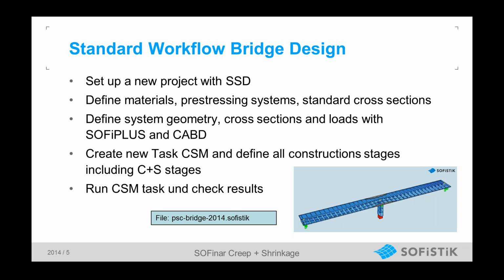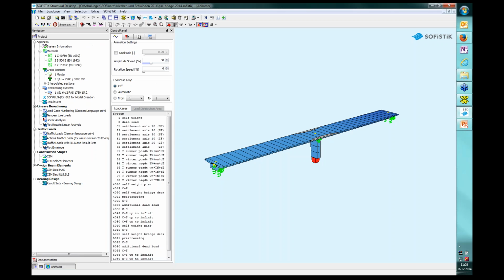Now, the next step inside SSD is to deal with construction stages. I think the construction stage manager is well known by everybody, so it's not necessary to introduce it to you, but nevertheless I will spend a few minutes on it, explaining what you have to do, especially with creep and shrinkage questions inside the construction stage manager. So let's start right away with this little pre-stressed concrete bridge.